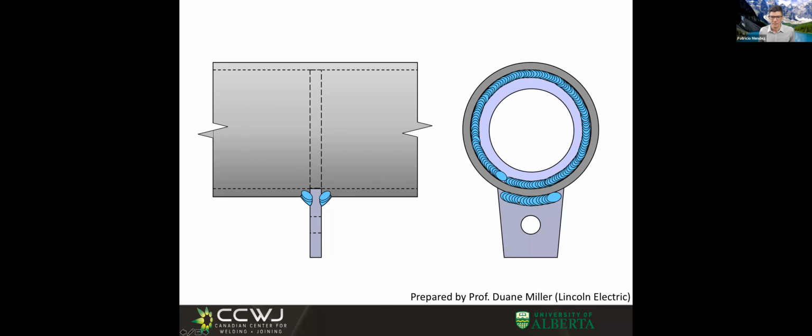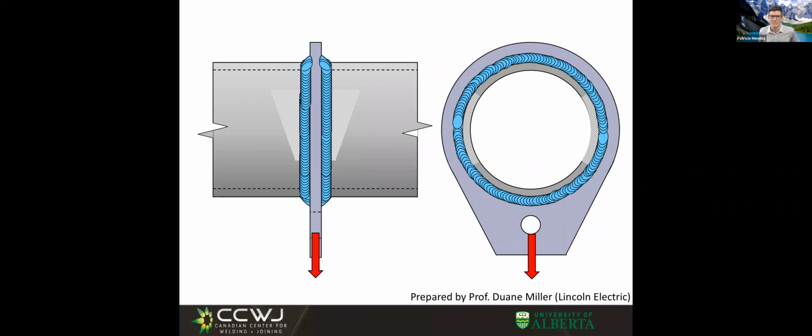In this case, if we put a stiffener ring, we would be transmitting the load to the vertical parts. And watch this. This is a very interesting thing. These welds here are going to be taking a lot of load because they're going on the stiff parts. But these other welds, they're on the more compliant parts of the pipe. Do I need them? Well, I'm going to show you this other one. And here we have the stiffener ring outside. Now that gets interesting, right?